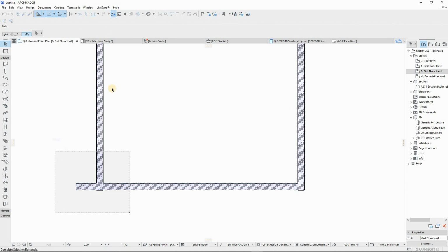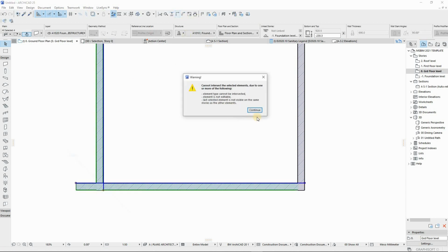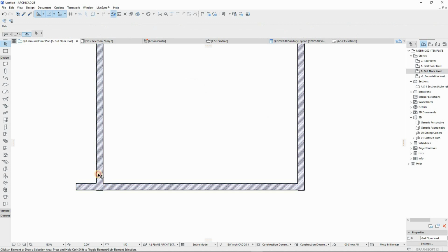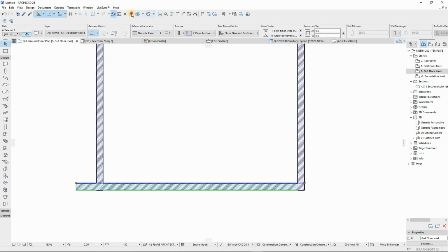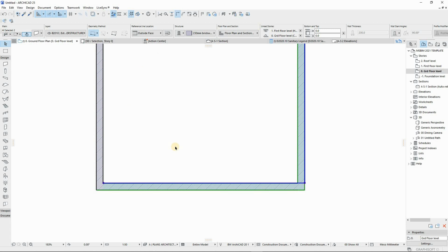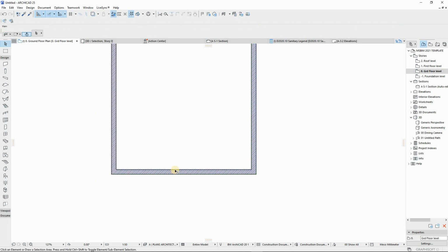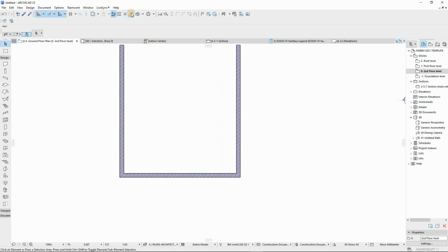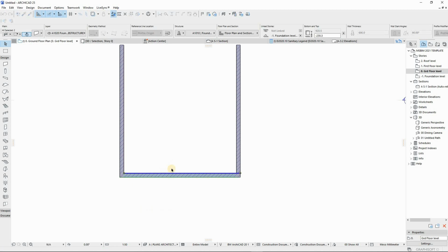Then what I'll do, I'll select this, or you can do it manual, unsuspend the group so that you can fillet everything once like that. Perfect. Then I'll again unsuspend groups to drag a copy to there, and then I'll say this should be 3.2